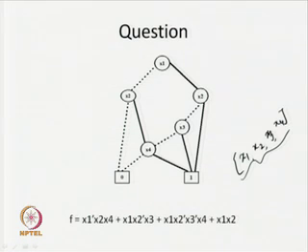So, what is the first term, x1 prime x2 x4? That means x1 equal to 0, x2 equal to 1, x4 equal to 1, the function will give me the value 1. Similarly, x1 x2 bar x3 will give me valuation 1, x1 x2 bar x3 bar x4 is another 1 valuation, and x1 and x2.